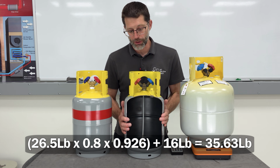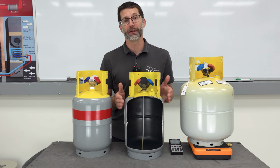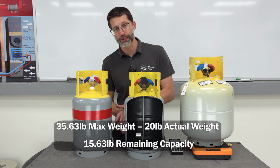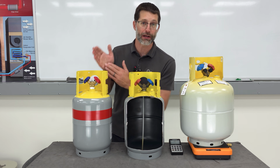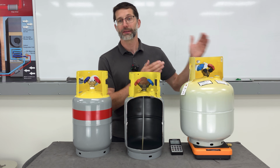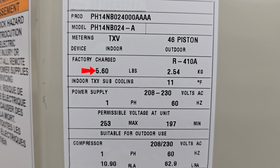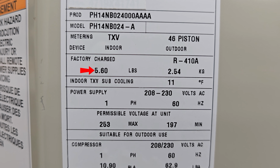So if you put this onto the scale and you have, say, 20 pounds, then that means that you have 15.63 more pounds of refrigerant left in the tank that you can add in, and you would compare that to, say, the factory charge on the outdoor unit and see if it has excessive line set length, or if it's just a short line set, it might just be the amount that the factory charges. And so you would just go ahead and monitor the scale as you're recovering.